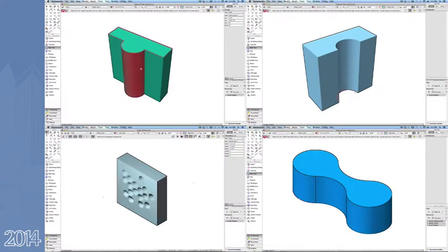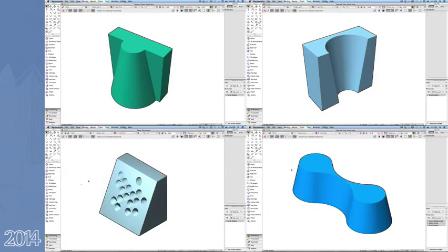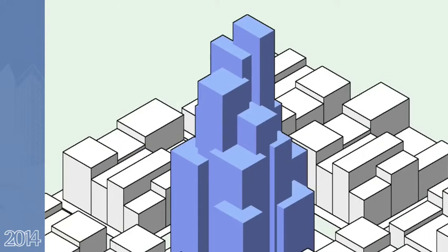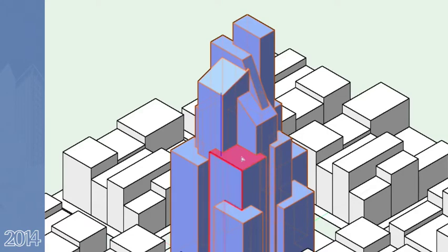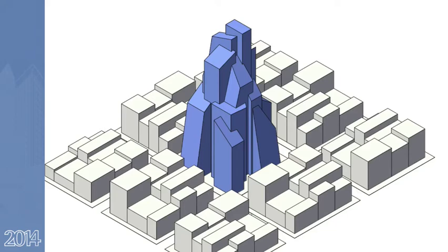Taper Face can be used to widen the base of solids and make tops narrow, and let you get very creative when modifying solid subtractions. In its simplest form, the tool will help you explore new design ideas by deforming solid objects. Let's take a look at this massing model and explore some design alternatives. With the Tangent Faces mode, you can quickly and directly pitch all the rooftops and explore different design alternatives for this building, something not easily accomplished previously.